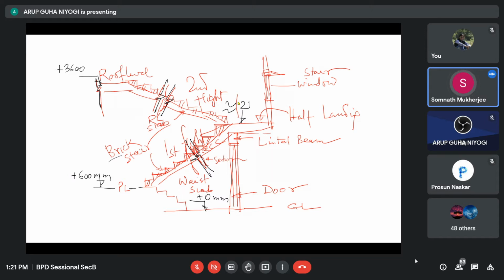With the dado level, we provide the window normally at 1200 level and above. Sometimes we can provide 1600 or 1400, but you have to consider whether you can open it or not. By standing you should be able to open the windows, so naturally the level will be slightly up. But we are providing a smaller width of window there, not the width we provide in other places. The width may be say 600 and the height around 600 to 750.